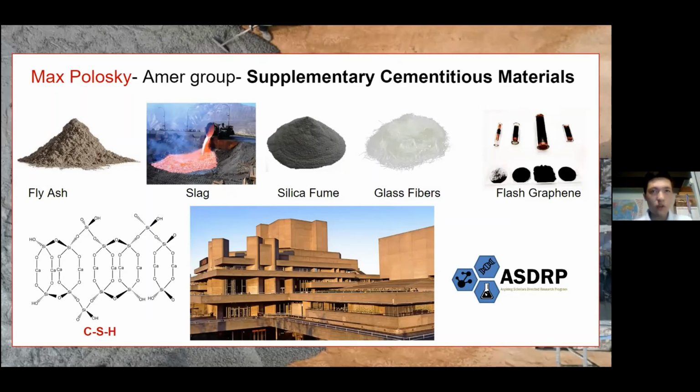So in the future, there are still many potential SCMs that we want to investigate. Many good SCMs, which are ones that will replace more cement, and these all have common characteristics. First of all, they must have silica or alumina to strengthen the concrete, and second of all, the silica and alumina should be in a non-crystalline form, making it easier to react and create the CSH compound that we want. And so, besides the ones that I mentioned here, we could look at SCMs such as rice husk ash, sugarcane ash, and tire-derived fuel ash.